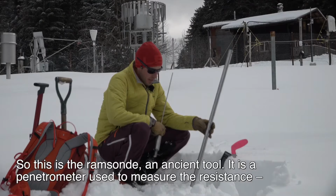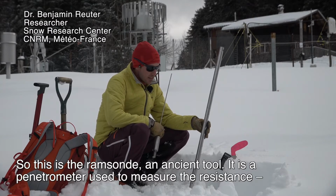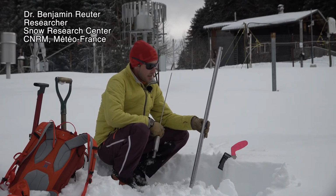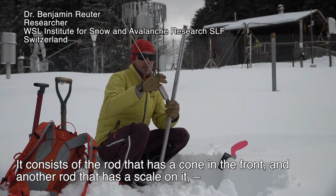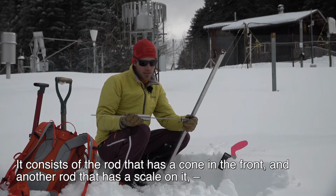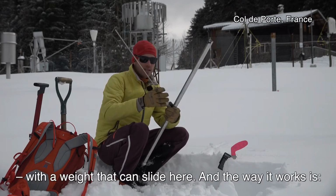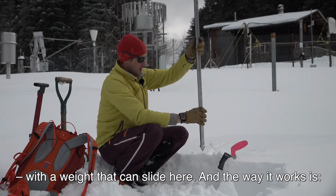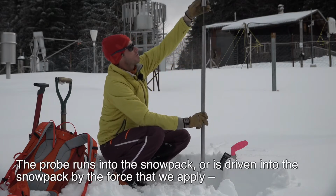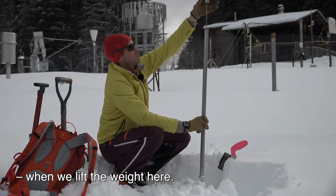All right, so this is the Rammsonde. It's an ancient tool. It's a penetrometer that is used to measure the resistance of snow layers in the snowpack, and consists of a rod that has a cone in the front and another rod that has a scale on it with a weight that can slide here. And the way it works is the probe is driven into the snowpack by the force that we apply when we lift the weight here.